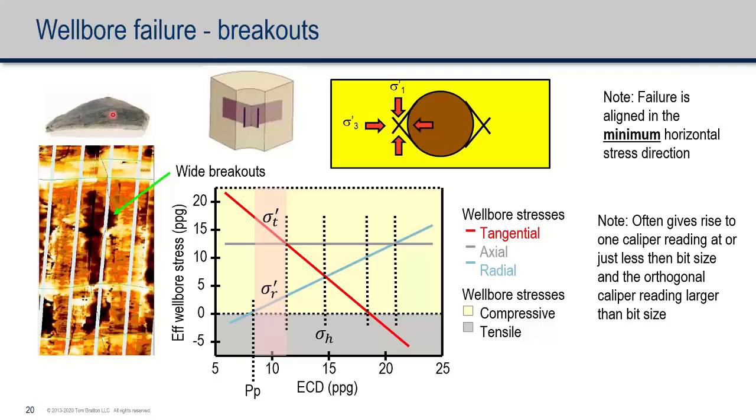This caving falls into the wellbore, gets filled with mud, and so your wellbore image shows this blurry, dark color, which is a mud-filled cavity because this material has failed and fallen into the wellbore. You get the breakout on the other side of the borehole. So half of it is here, and the other half is over here.